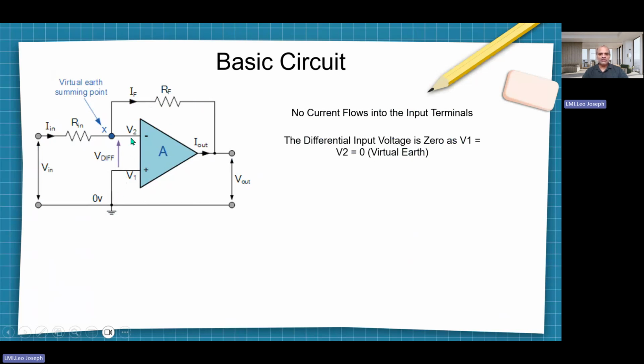So from here, what happened? This positive terminal is grounded, so you will get some minimum amount of current here also. That will come here, and you get it at this end. So the feedback resistance current, if you measure it, is nothing but the difference of these two currents. But ultimately, as the terminal here is grounded, automatically this current is zero. So which current will flow through the RF? The output current is said to flow through the RF and go to the ground.